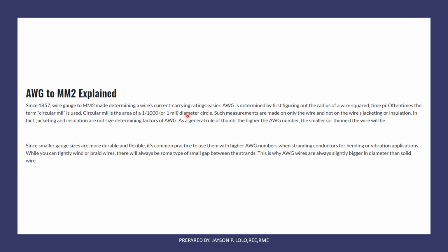Okay, but since we are in building wiring or building electrical, we are considering building cables only. So we are using mm squared as the base size or gauge size of the wire. Such measurements are made on only the wire and not on the wire jacketing or insulation.